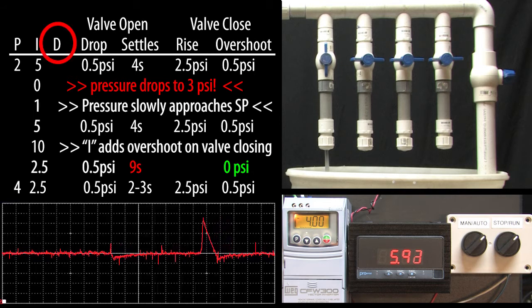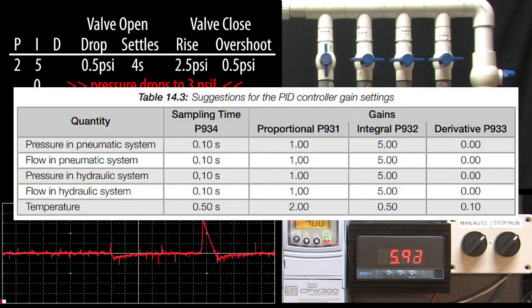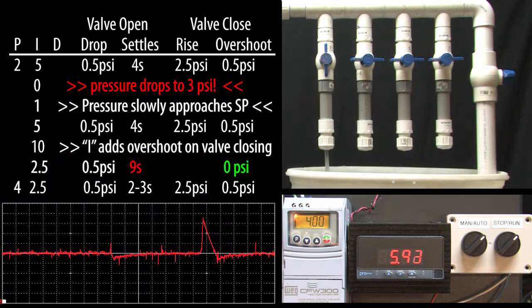Now what about the D term? Well, it's rare that you'll ever need a D term in an industrial application that uses AC motors. The D term is more important in high-speed applications like robotics and also temperature. It allows you to push the P and the I terms right up to being unstable because the D term moderates fast changes. It looks at how fast things are changing and slows them down a little when they get too large. The point here is, start with the recommended default values in the WEG programming manual, and then don't be afraid to try experiments like this. It's how you learn what your system's capable of and how hard you can push it to get the best possible performance. But what if you don't have an oscilloscope?